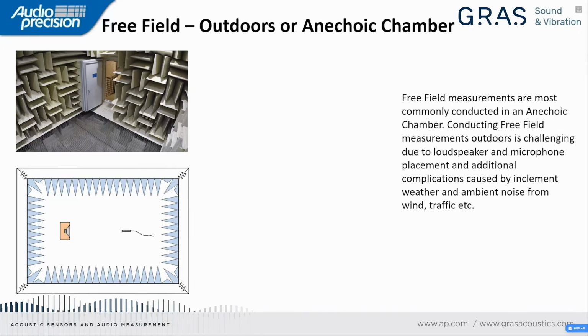This lower frequency limit can be estimated from another rule of thumb. To absorb sound of a given frequency, the significant dimension of the absorptive material must be at least 1/4 of the wavelength. Based on the quarter wavelength rule and the speed of sound in air at room temperature, 1 meter long wedges can effectively absorb sound above approximately 86 Hz in frequency. For practical reasons and cost, it is rare to find an anechoic chamber with a lower limiting frequency below 60 to 80 Hz.